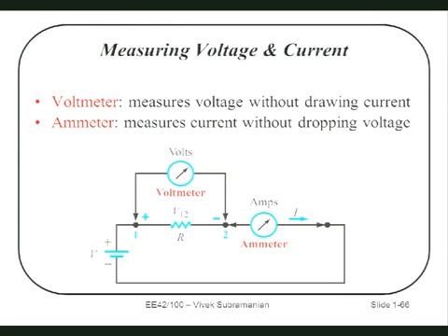Okay? So this is why you do not want to take your multimeter in an ammeter range and put it across your battery. Because that means you're putting a 0.1 ohm resistor across your battery. What happens when you do that? It's essentially a short on your battery. Most ammeters have short circuit protection, so the ammeter will be fine. The ammeter won't get damaged, but you'll discharge your battery relatively quickly. And it'll heat up a little. So that's not so good.